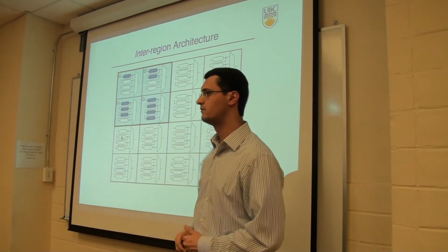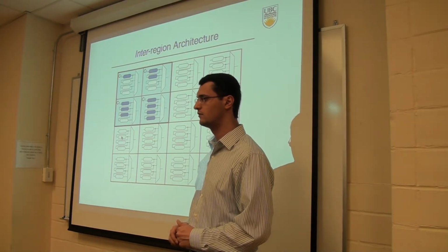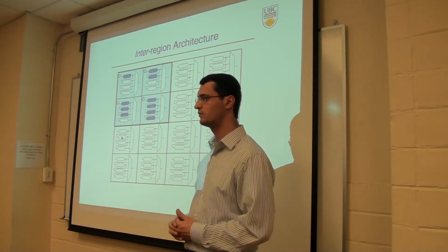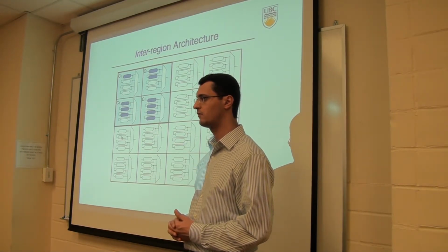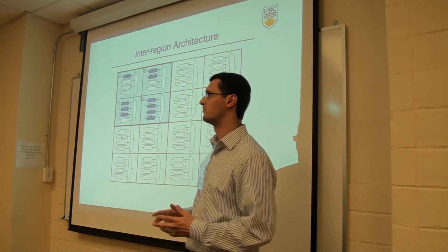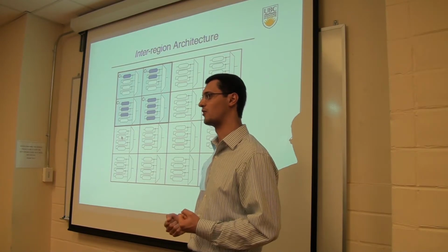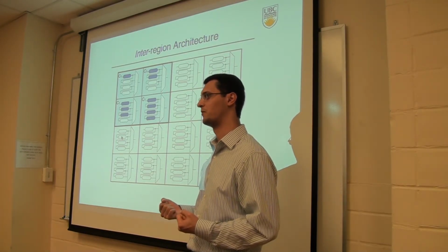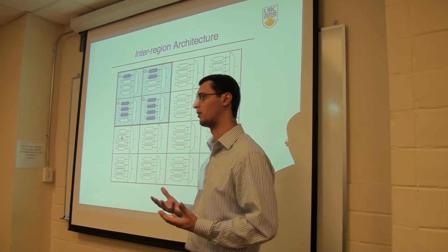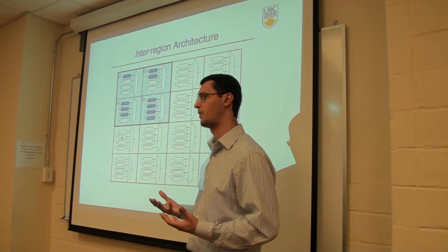Just a question. I think you have an assumption that there's another control signal that activates the circuit itself. Is that correct? That while it's powering up, it can't actually be wanting to change its state, for example. Yeah. So, when the architecture is perfect, what we assume is that there should be a handshaking signal that tells that the power-gated domain is turned on, so the circuit itself knows that it can begin computing.